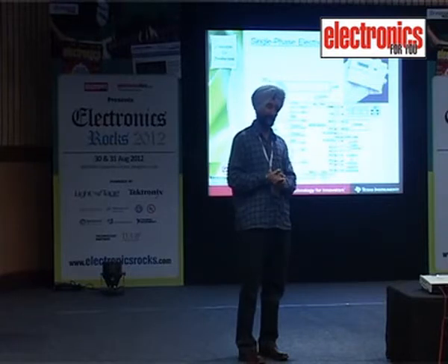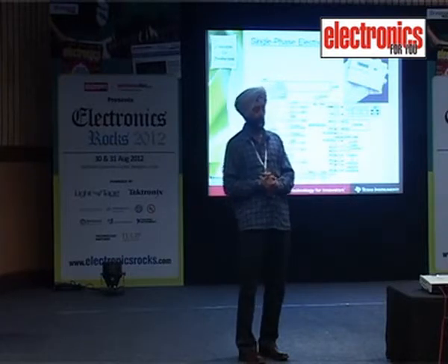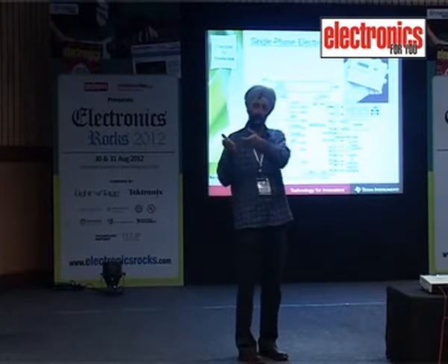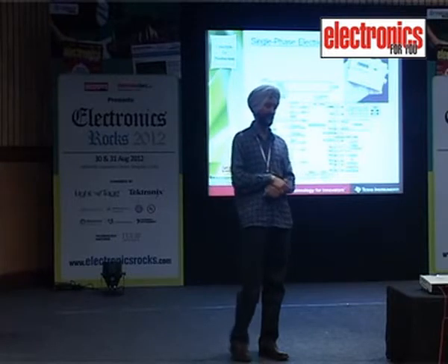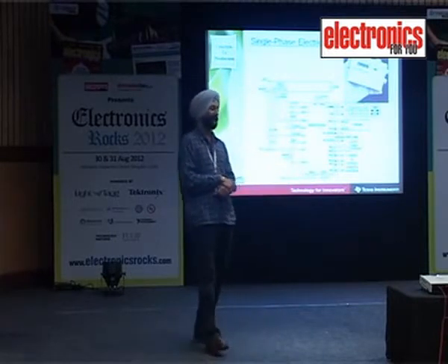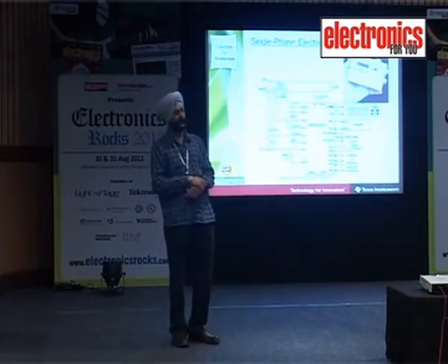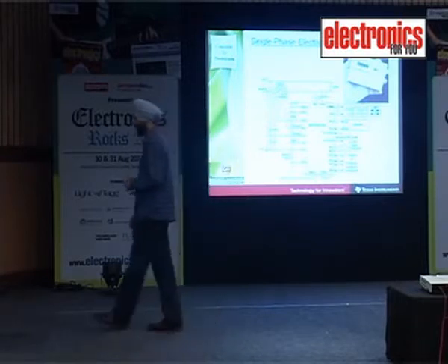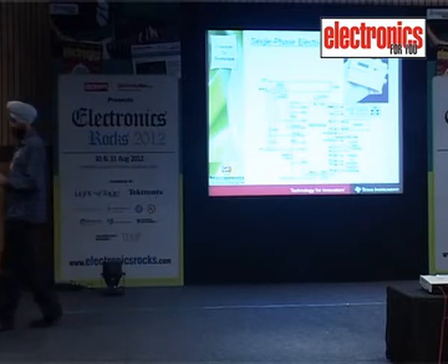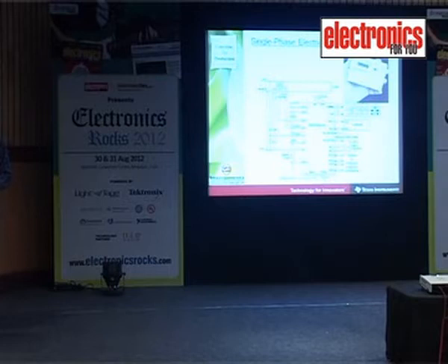Now in MSP430, since it takes very low power, it can even draw the power from the current sensor itself, let's say a CT, right, current transformer. That output is enough to power up the MSP430, and based on that power it will continue to do the measurements, so that ultimately it will be able to detect your tampering also, and it will continue the measurements also.